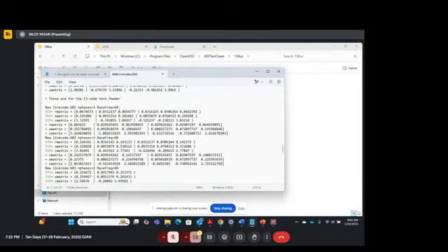So if you see redirect, that means it calls this particular file again. So node circuit.dss calls this particular file. And then you see the line code defined here. It's like 601 that I was talking about, 601, 602, the different phases. The R matrix, X matrix, and C matrix are defined here. So it should be exactly equal to what you see in the docs file.